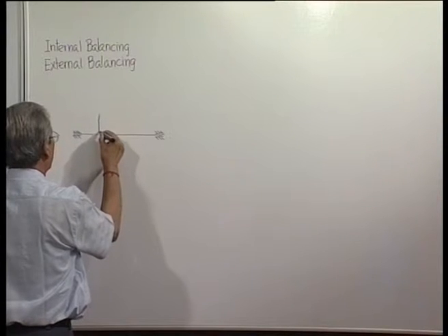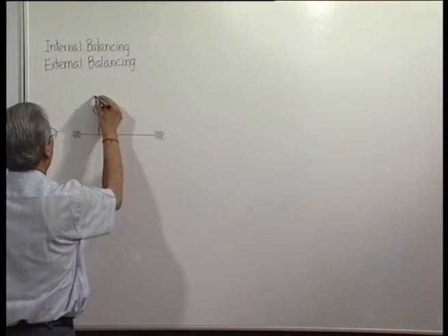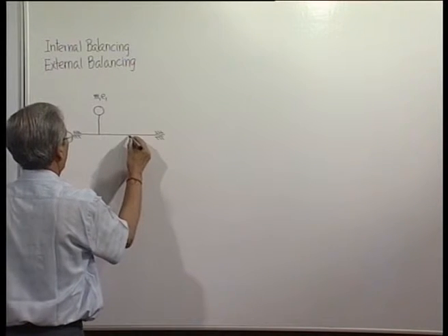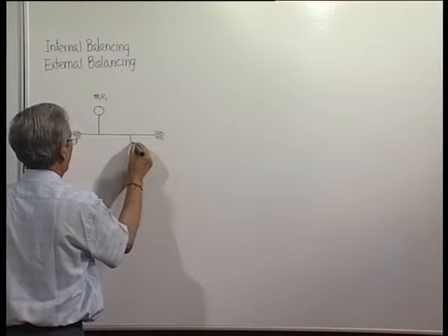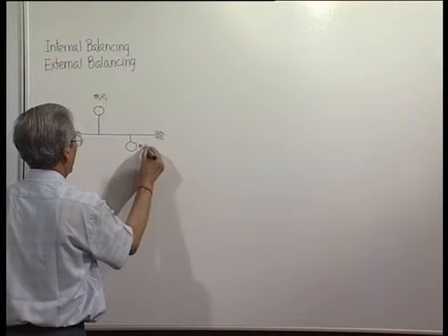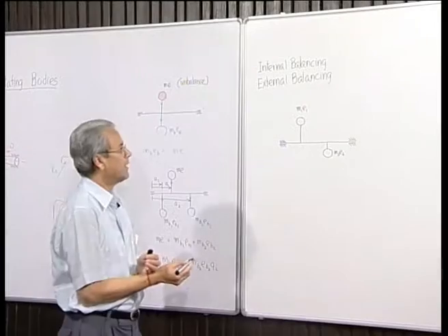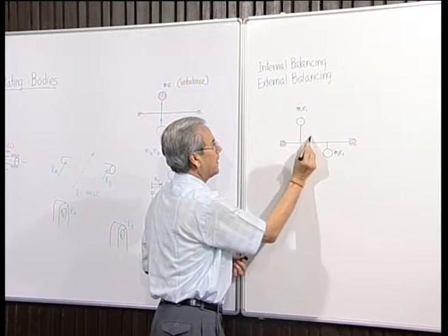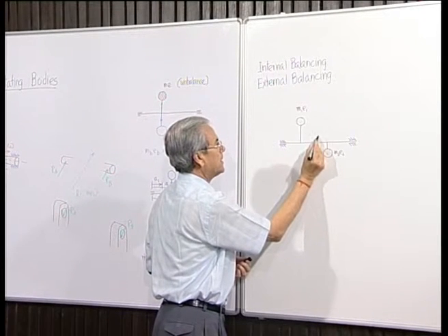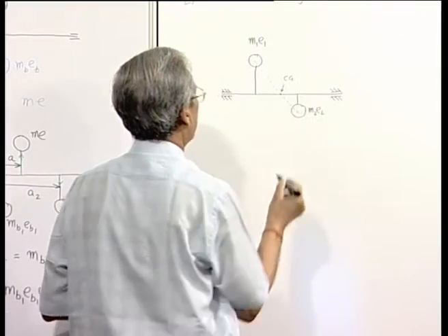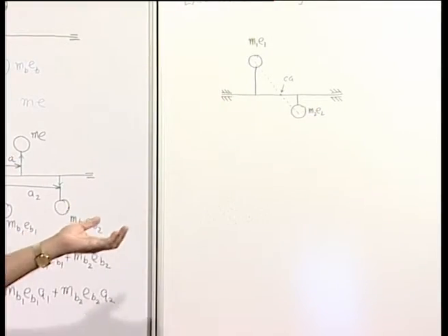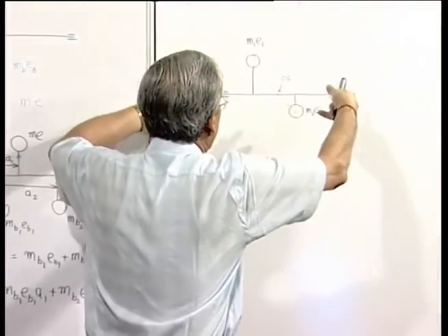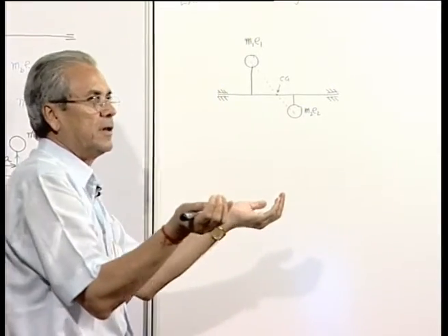Now, if we have two unbalances in such a way that their center of mass is here, then this system in static condition it will appear that it is balanced, because you can put it in any angular position on a free bearing, it will remain there.